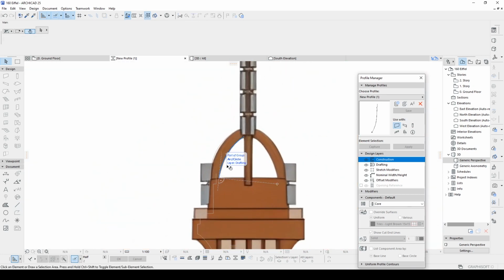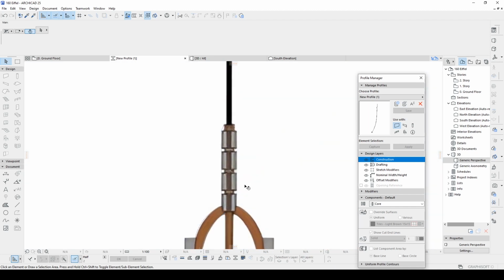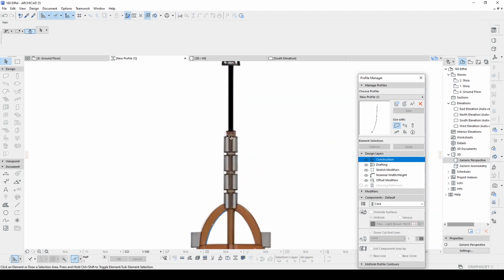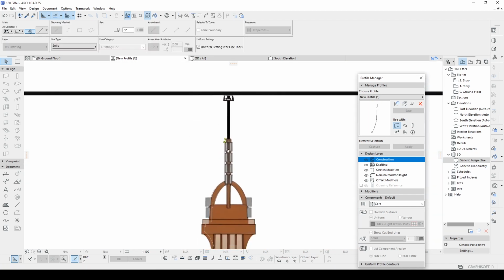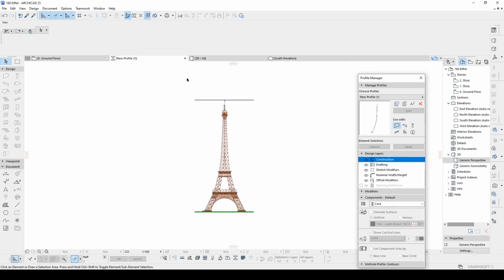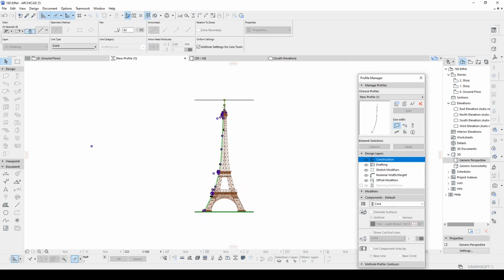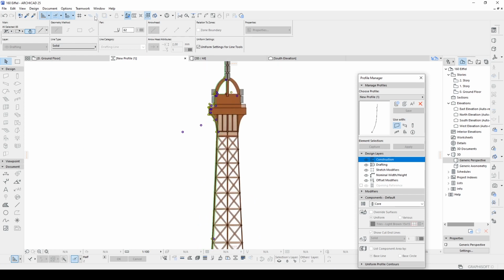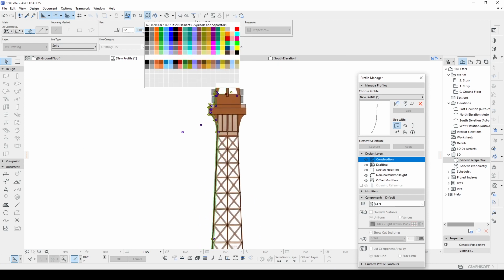By the way, if you can't see your lines, or in order to see them easier, you can change the line shape, line thickness or color. To do that, you can select all of your lines and go to pen here and change your pen with one of them. For instance, you can create a new pen type. For example, this